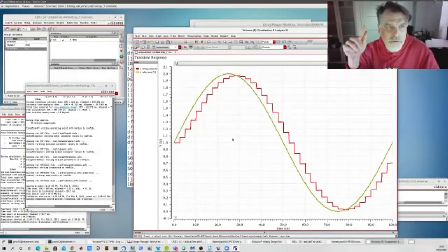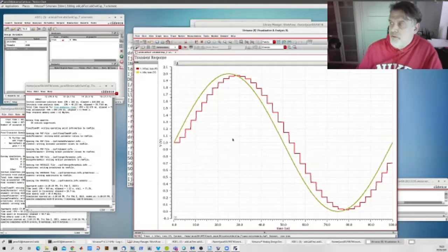We had R equal to T divided by C, so that's 1 over F times C. And now I increased F, I reduced R, I moved the pole to higher frequencies, and that's what we see here also now. The low frequency input passes through the system much more conveniently here, and we only have a small phase delay from the filter.